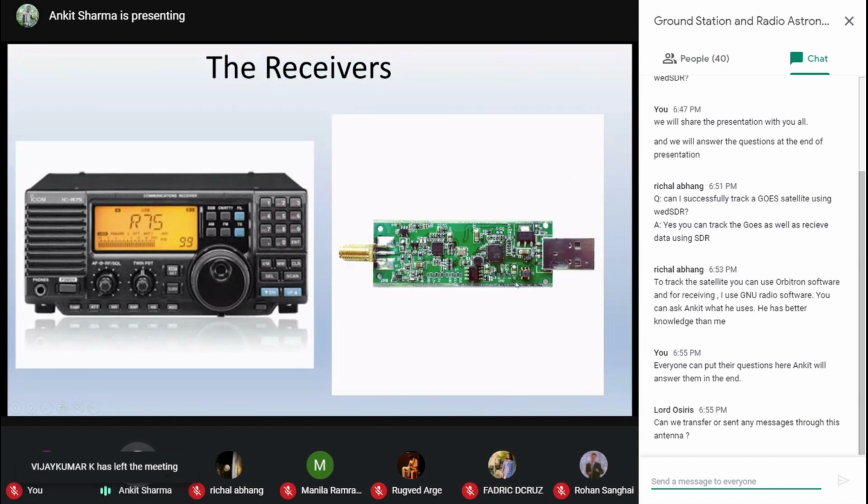And then that software receives the signal through the USB port, and we can operate through it. Since the signals become digital, the losses are less, and that's why we always recommend that this part should have a longer USB cable and a shorter coax cable. Basically, we recommend this generally. This tweak also helps in reducing the noises around, which can enter through your coax cable, because no coax cables are lossless.